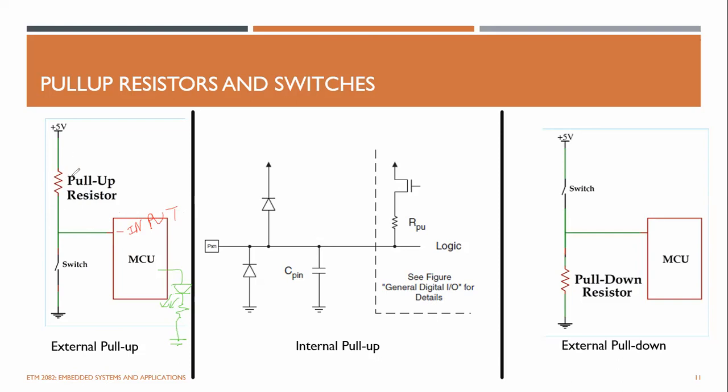So now there's no current flowing, so this is at 5 volt. This holds the voltage because V equals IR, and this impedance is infinite. Like I mentioned, there's a high impedance connected to the ground, and this resistance is very high. So literally no current will flow.